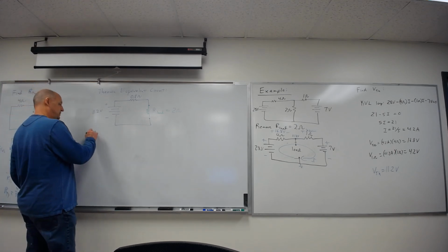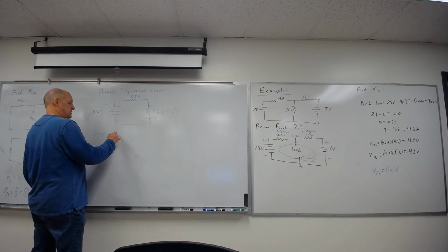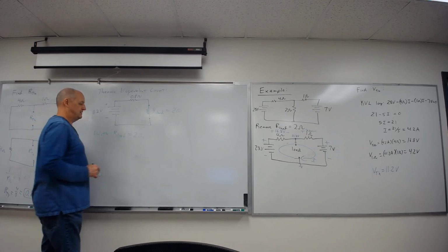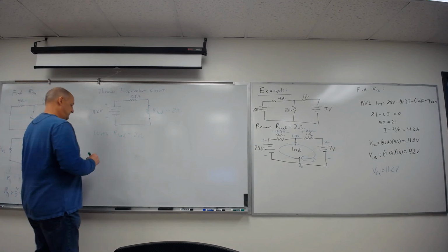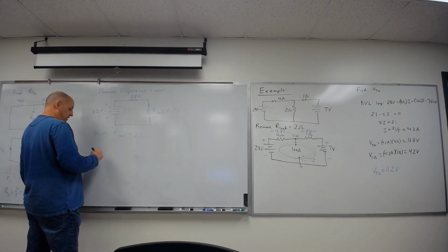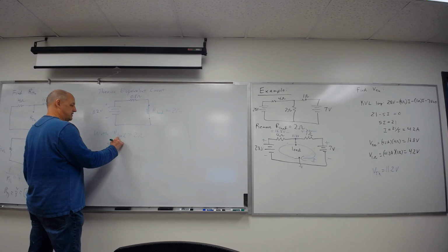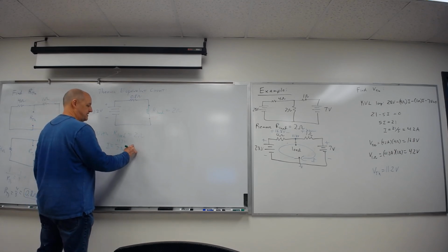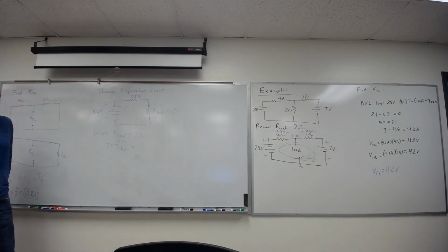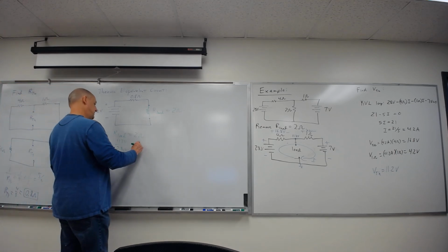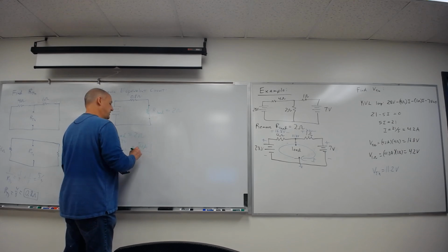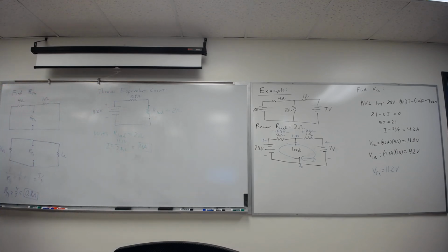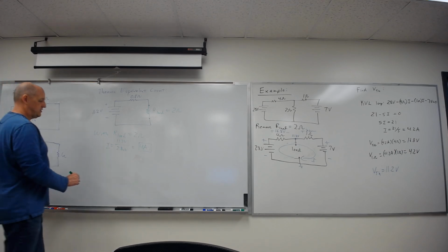So, with my load at 2 ohms, I can find whatever I want, right? The current in the circuit, according to Ohm's law, is 11.2 volts over 2.8 ohms. Right? Just take this voltage over the total resistance. 11.2 volts over 2.8 is 4 amps, which I believe is what we got in all the other problems with that same circuit.